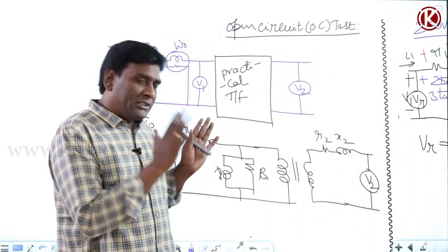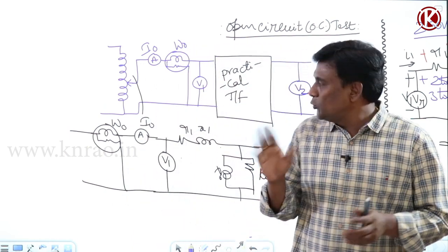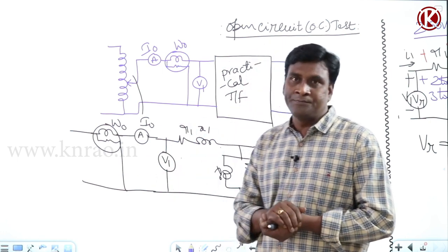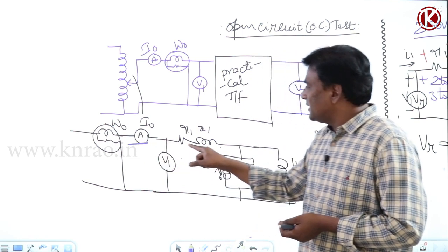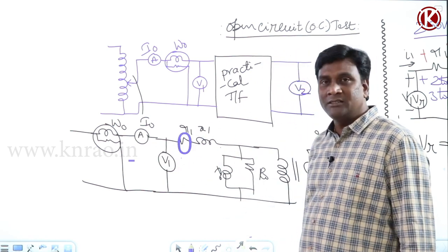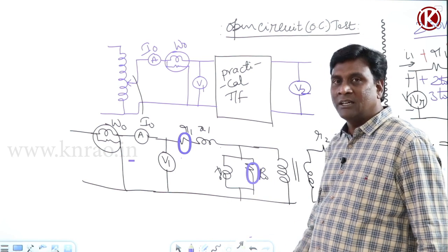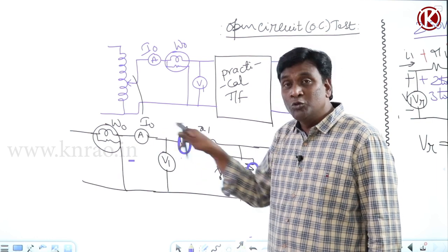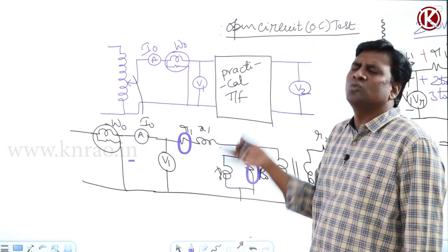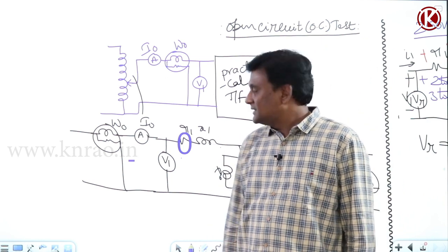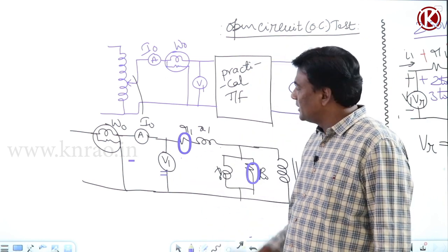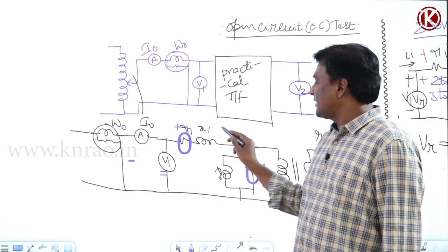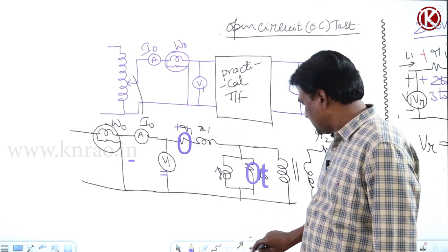So if I just have a small recap. We started like this. My wattmeter error will be there, and voltmeter error will be there in consideration. Because my wattmeter will measure copper losses here and core losses here, but later we found that the component of wattmeter reading representing primary winding copper loss due to no load current is negligible compared to rated core loss, so neglect this. Now second thing is my voltmeter will record voltage across this plus voltage across this.